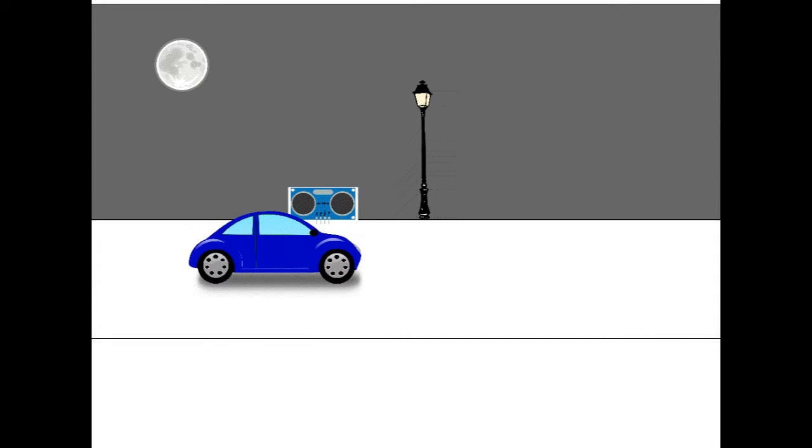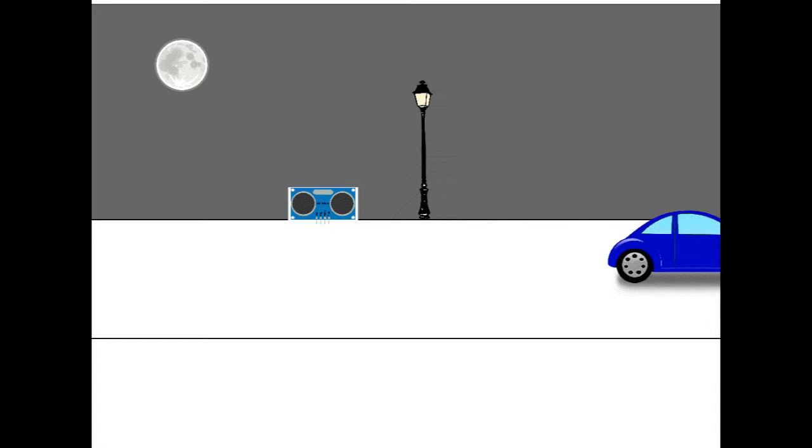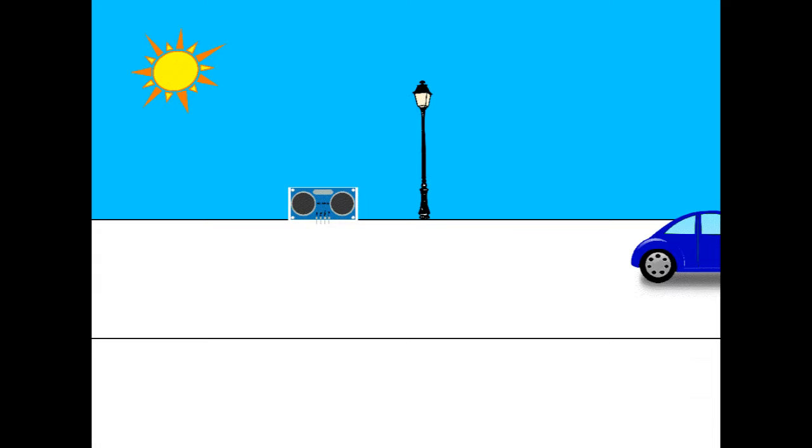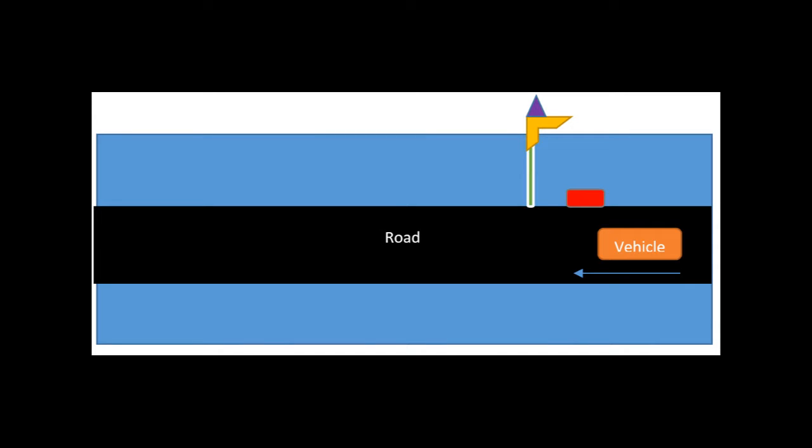Automatic streetlight control. This project illustrates the streetlight control system depending on the vehicle movement. This is an energy efficient method of controlling the street lights by detecting the vehicle movement on the roads. A set of ultrasonic sensors are placed on the roads to detect the vehicle movement. The sensed data is processed in the microcontroller and accordingly it switches the street lights. Also, an LDR is used to save energy during the daytime by not activating the street lights during the day.